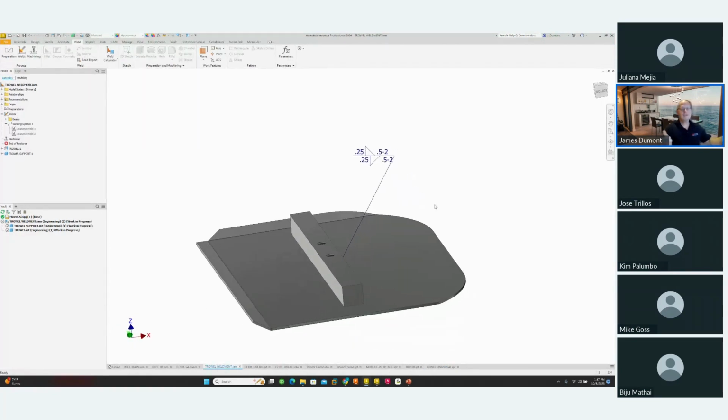Well, can we get a shout out? How many people are doing weldments inside of Inventor? I'm going to say mostly all of you should be doing weldments. Yep. Okay. So you have always had the ability to add the 3D annotations for the welds. And you'll see that under welds, you'll see the weld symbol, and you'll see them here, and we have our annotation.